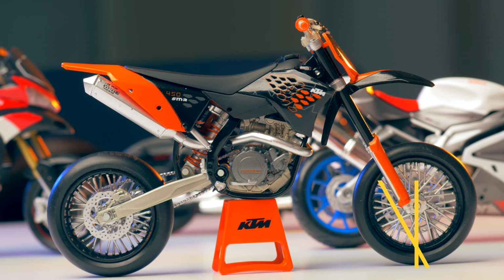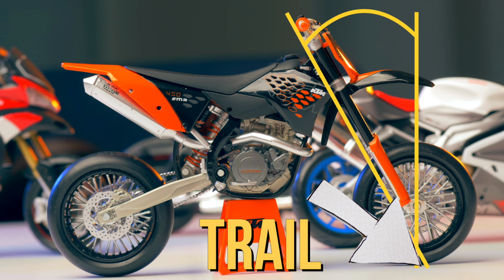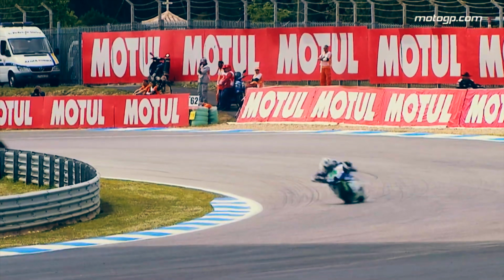So the rake angle is the angle between the steering axis with respect to a vertical line. The wheel plus tire has a certain diameter, and from these measures we derive a very important measure called trail. Trail is a measurement of how far the contact patch of the front tire is behind the point where the steering axis hits the ground.